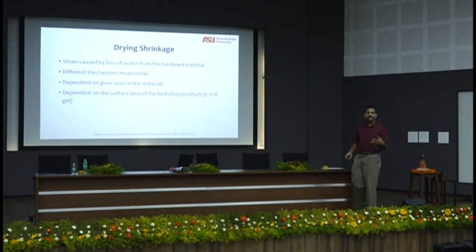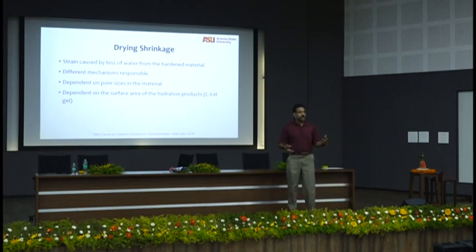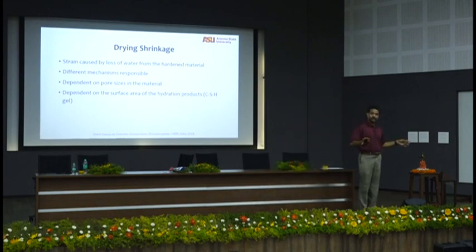Size of the pore. Now, why is size of the pore important for shrinkage? Shrinkage is a volume change. Nobody should ever be bothered about just the change in volume, and you should let concrete change its volume if you did not restrain the structure, right? If there is no restraint, no stresses will be developed. If no stresses will be developed, no cracking happens. So, we are not worried about stresses being developed under a free state, but we are worried about stresses being developed under a restrained state.